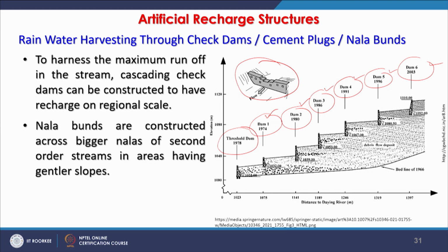So, as I have said, on very high order streams these should not be constructed, because the water will be too much to handle for these check dams. These are not truly very much engineered, but simple engineering solutions. So, they cannot face that kind of pressure of water.